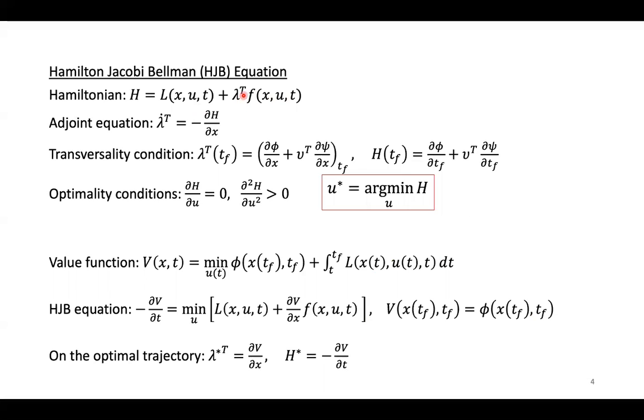And you can actually derive the dynamics for this co-state by essentially taking the partial of this Hamiltonian with regards to state and multiplying it with -1. And that is what is called the adjoint equation for this optimal control problem. Furthermore, you would arrive at the boundary conditions for the co-state and the Hamiltonian using this terminal cost function, and this is the terminal condition for the optimal control problem. And here, nu is a multiplier. This is just standard procedure.